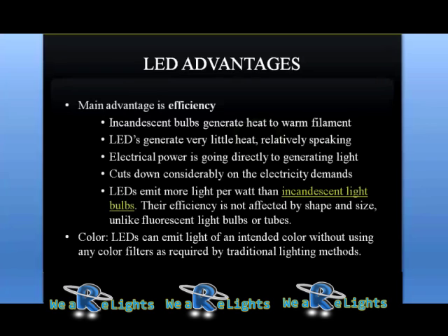light. A typical T8 fluorescent tube pulls 32 watts. The equivalent T8 or T10 LED tube will pull 15 watts and provide equivalent lumens, if not more, than the old bulb. In virtually every lighting environment, the total energy required to create the identical lumen count with LEDs is reduced by 30 to 80%.